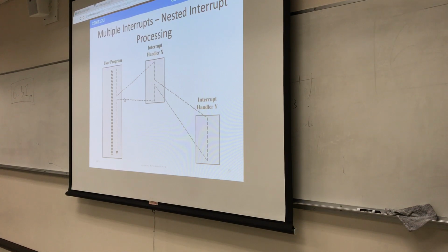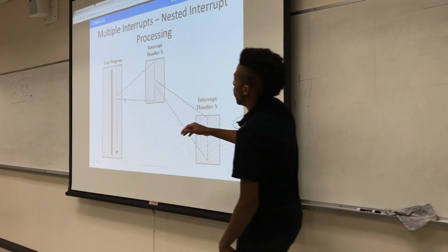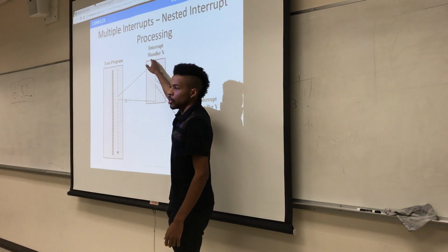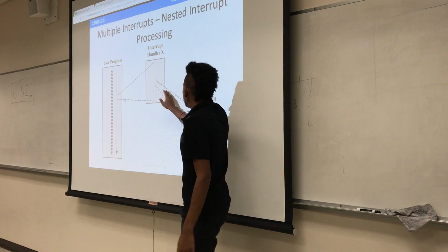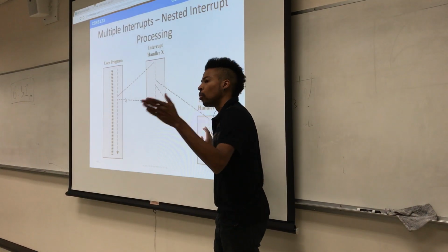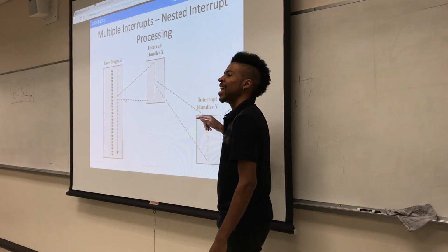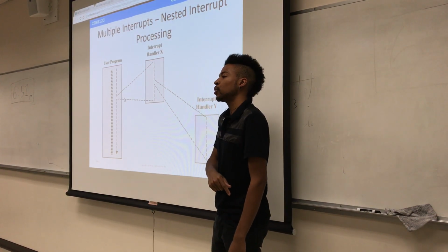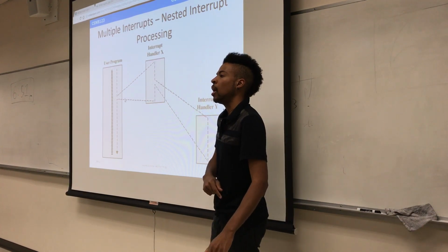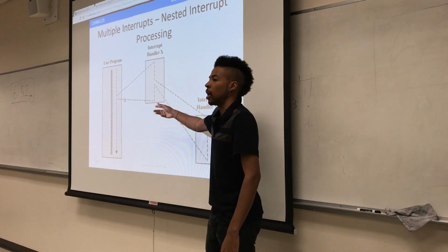Yeah. So to re-elaborate, if anyone didn't hear that: if you don't have a priority system, then an interrupt of any type can come in and spawn you off. Say a low priority interrupt is doing its thing, then another low priority interrupt comes in, and another. Then a high priority item comes in, and you start running that one. Then another low priority comes in. Now that higher priority one is starved and can't finish its service routine, while your lower priority interrupts keep coming in front of it.